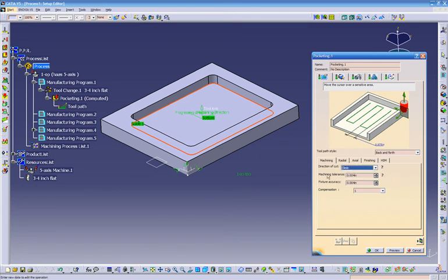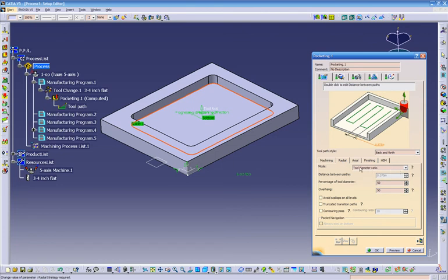I never change it. Over here is the tolerance. You can see over there. Radial is asking us over here the tool diameter. So you just put over here kind of like a step over. So right now it's 50%. So the step over ratio is 50%. Or we can put to distance. So right now we put step over 375. Step over from here to here, we get 375. Or we can put the step over ratio or maximum distance.